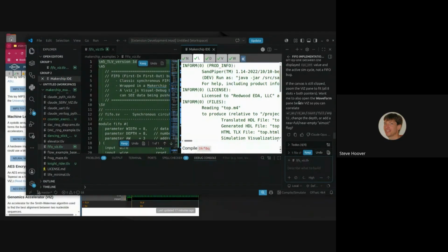So I can actually talk about specifically clock gating in TL-Verilog because it's way easier to do clock gating in TL-Verilog. But you can certainly do Verilog or TL-Verilog coding as you wish. You can definitely implement clock gating and simulate it. The point is Makerchip itself does not run power analysis or any of those backend tools.